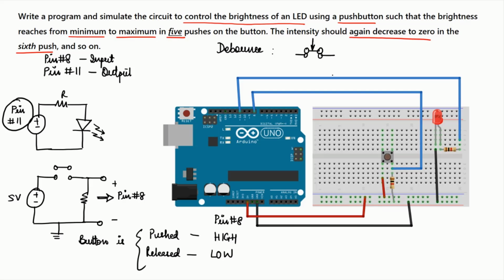So push buttons often generate spurious open or closed transitions when they are pressed. This is simply because of a mechanical or physical constraint. These transitions may be read as multiple presses, as if the microcontroller thinks that the button has been pressed multiple times in a very short duration, but it was just one press. It is the physical limitation which has led to this confusion.